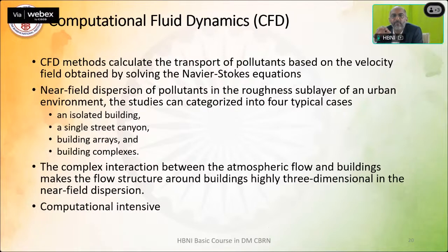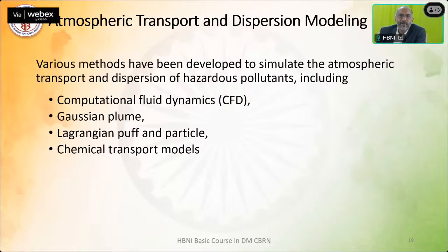how they are useful, what their merits and demerits are. I explained that the CFD model is used when you are supposed to assess release conditions in a small area where the dispersion is dictated by local geometries, basically buildings and the complexities involved. Where those kinds of details influence the dispersion, you use a computational fluid dynamic model. I also told you it is computationally intensive, so based on your need, you choose whichever of these four models is applicable.